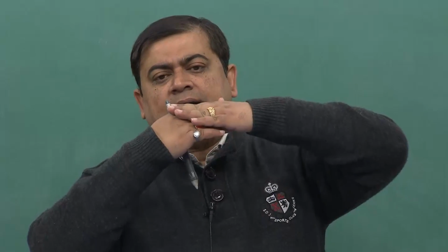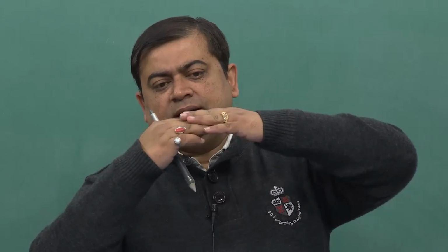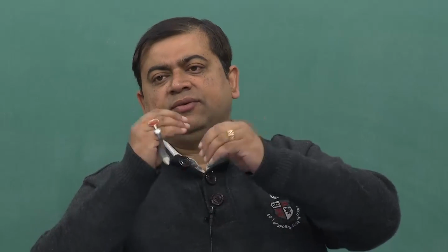So, typically the practice that is followed is, for a spherical pattern, for example, or for a very large casting, let us say a casting of a wheel, you should have a half and half pattern. So, therefore, there is an upper half of the mold and a lower half of the mold. Lower half is normally known as drag and the upper half is the cope, and then these two have a parting line, but the pattern is kept in a manner so that you have the split pattern. You have half inside the lower portion and half the upper portion.